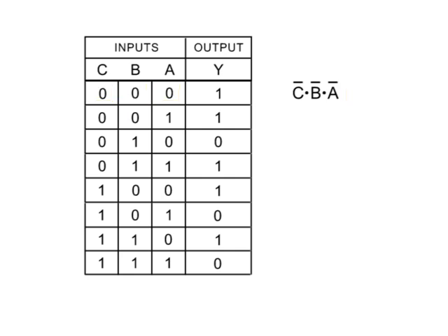The next instance of a logical 1 output is row 2. Applying the same method, the product term would be not C, not B, and A. Continue down the table until all product terms for possible logical 1 outputs have been created.